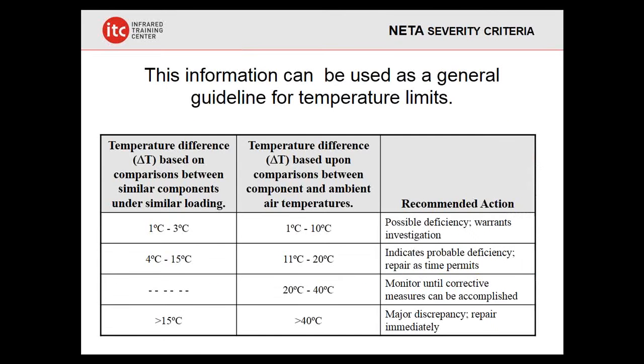And so when we talk about, in our Level 1 training classes, temperature-based prioritization, we take it with a grain of salt, in that the thermographer needs to understand that knowing exactly how hot it is isn't the only consideration. That's right. These charts are all over the place. This one's from NETA. Some companies will make their own charts. We just want to leave you with this: if you're using infrared already, consider more than just the temperature of the fault when it comes to prioritizing something.